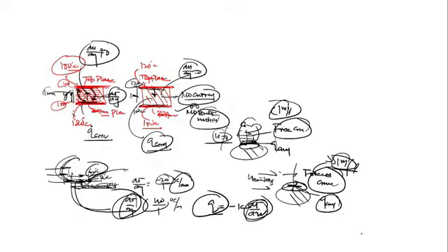So please tell me, the temperature gradient at the wall at y equal to 0, dT upon dy at y equal to 0. Listen, so is the temperature gradient at the wall higher in free convection or forced convection? As I told you via this example, here the temperature gradient at the wall is minus 20 and here the temperature gradient is minus 40.